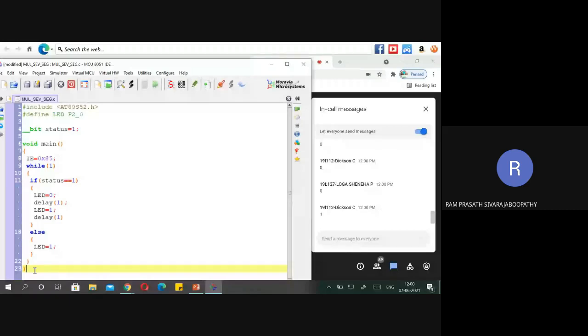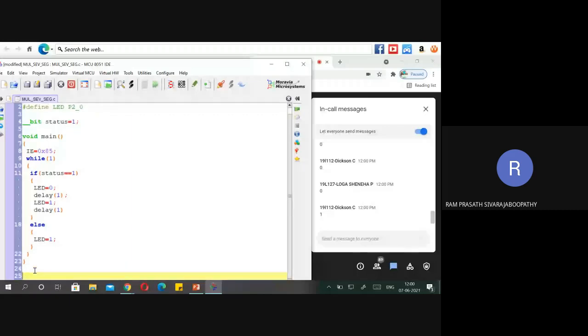Very good. Now I am going to write the interrupt program, the ISR. So far I have declared many functions. Now I am going to write the interrupt service routine function. It's very important, kindly listen carefully. There is some syntax we have to follow in embedded C to write an interrupt service routine. It should not accept any input and it should not return any value.